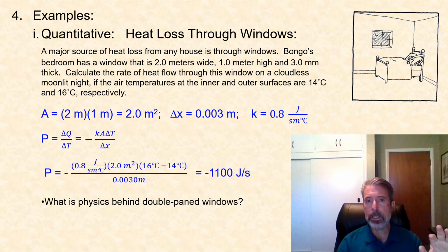So the double pane windows, all they really do, just like clothing, they trap a layer of air that doesn't get replaced. You'll see that nowadays in your even more expensive windows, you can buy windows that have the casing not filled with air, but filled with a low pressure gas that is even a better insulator than air, with a lower thermal conductivity constant than air.